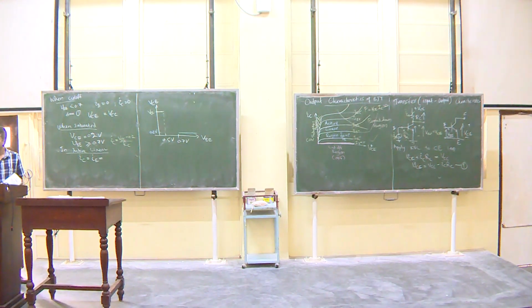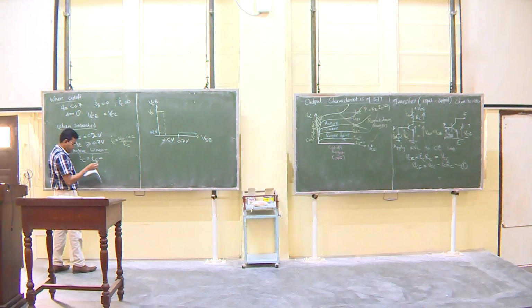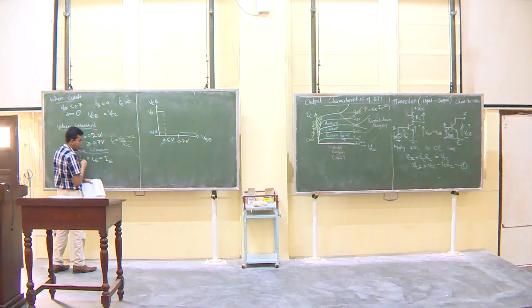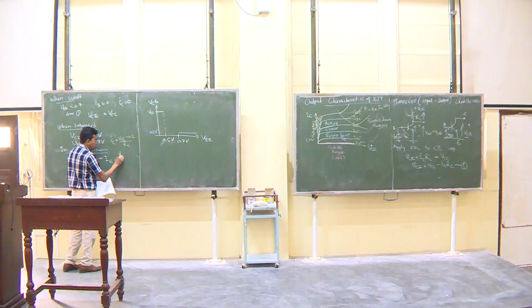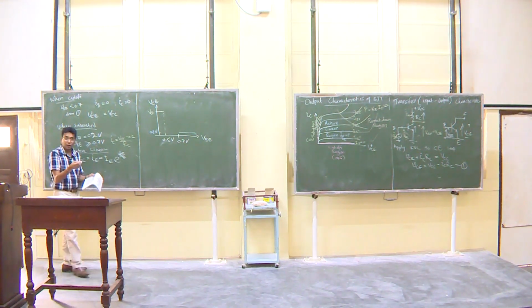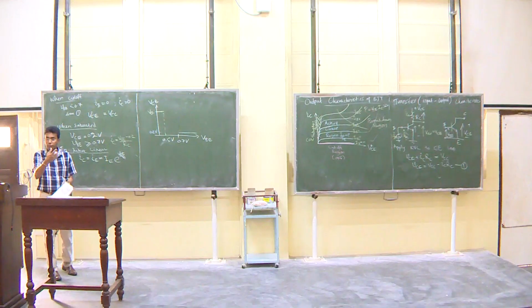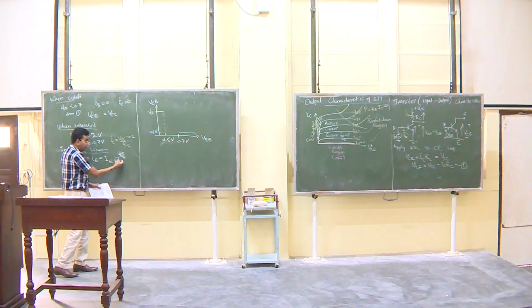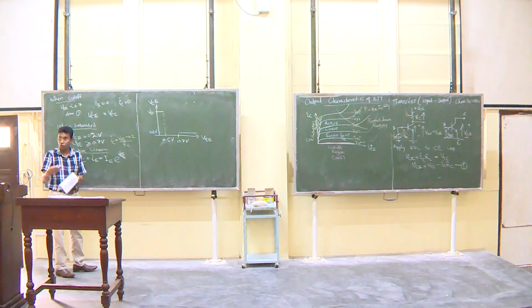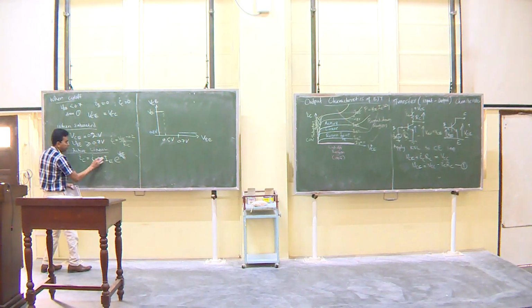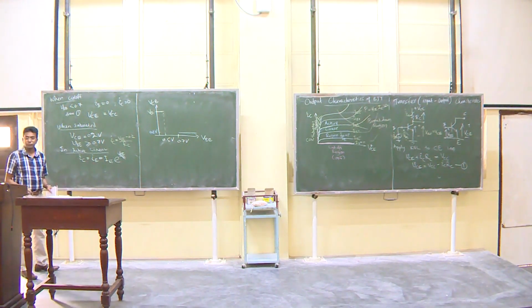And we know IE obeys the Ebers-Moll criteria, forward bias current, right. So, this is equal to reverse saturation current IS e to the VBE over VT minus 1. If you want, you can have it, but remember this is in picoamperes. Now, IB in saturation is much bigger, in milliamperes. So, I can easily ignore that minus 1 part. You can keep that minus 1, it will make the model more complicated, but this is good enough, so I will put it almost equal to.